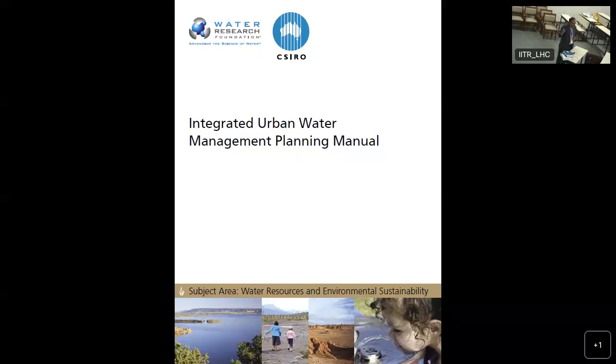There are two ways of providing wastewater. One is that you treat the wastewater to a high standard and then you dump it into the reservoir. That is the indirect potable application. In some places, they also try treating directly to a very high quality and then injecting it into the network system. The community is not very much interested in that type of system because there is still a yuck factor about the usage of highly treated wastewater.